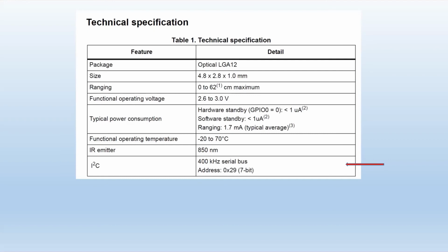And it gives you the unique address of that particular module. Very low current consumption. But the biggest issue right now for us is this one. Unlike many other modules, it works on a voltage between 2.8 and 3 volts only.